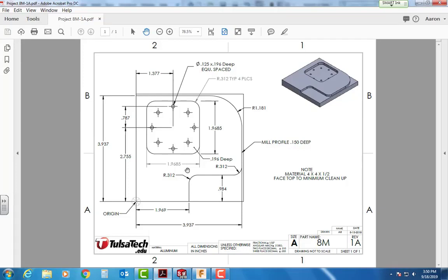Now, one thing that's going to help me before I start is I want to know what the width of my box, my pocket, is, divided by 2. Because when I go to constrain this left side and this bottom side, if you'll notice, the dimensions are called out to the center of the pocket. So in order to do that correctly, I'm going to take this dimension right here and subtract half the pocket. So let's pull up our calculator.